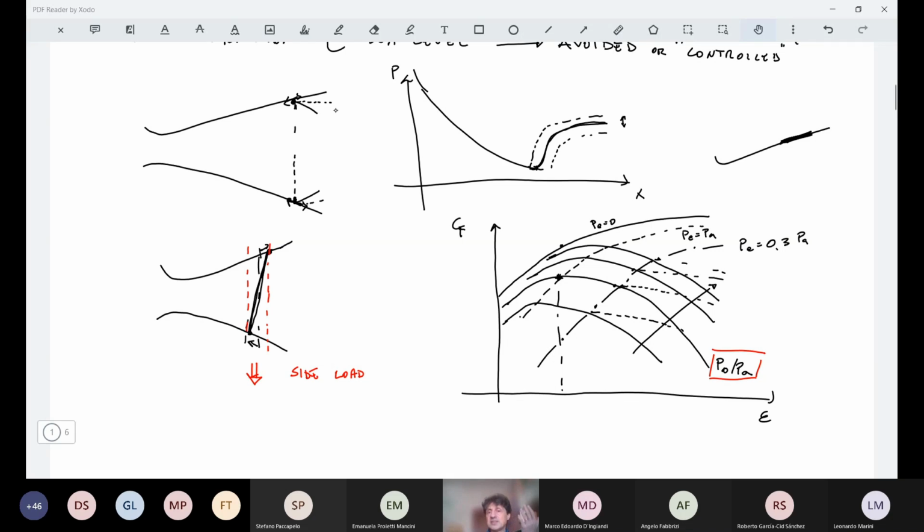So to achieve the maximum performance during vacuum operation, if these are the values of pressure that I have to deal with, I should achieve the maximum epsilon that is allowed. And in this case, it is this one, before we have flow separation. So we start here at this epsilon. This is our maximum epsilon for our P0 starting from sea level.